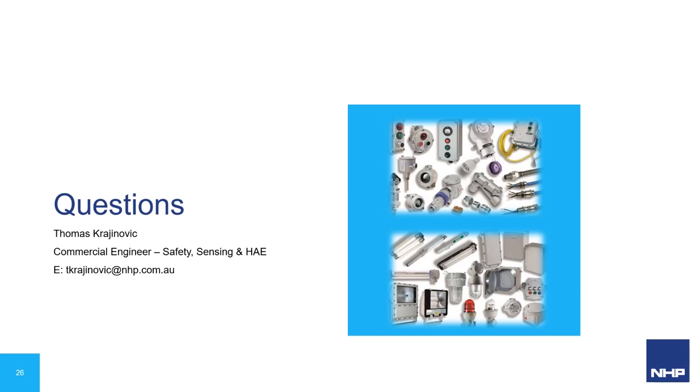So not necessarily. It depends what the instrument is. If it's hazardous area rated and it's suitable for use in zone 1, then it's okay. In most cases, if the sensor itself is EXI rated, you would need to use it with a barrier. That's how it achieves its protection effectively. But if it was something else like EXD rated, which there are some unique EXD rated sensors, and it's suitable for zone 1, then it would be able to be used in that environment as long as you follow all the conditions around its certification.